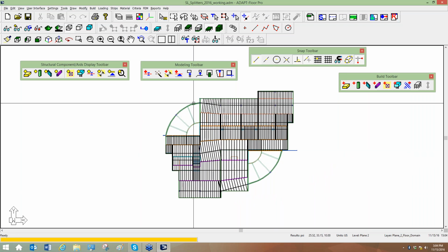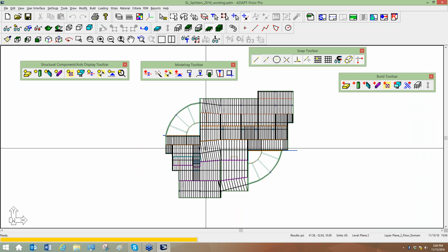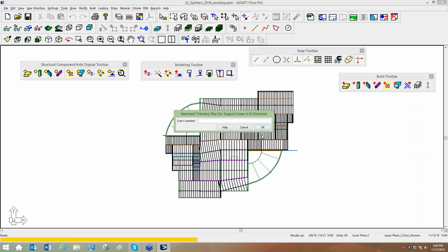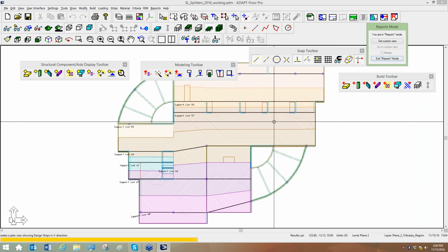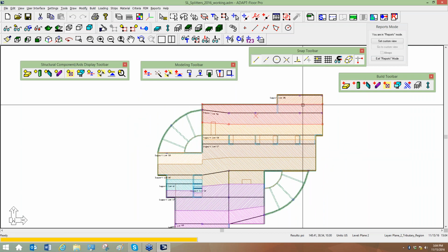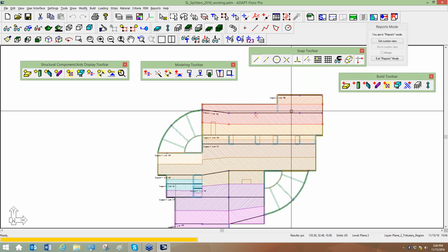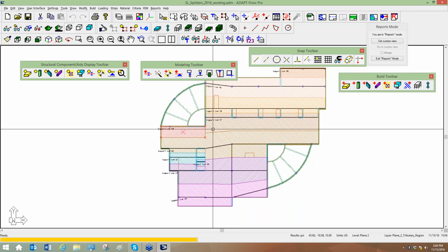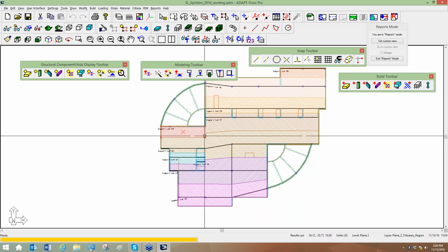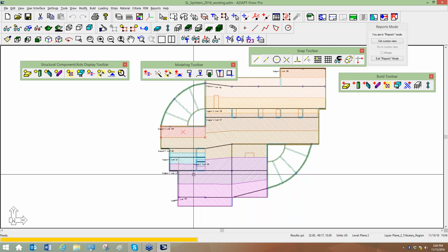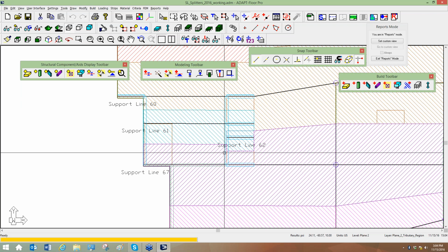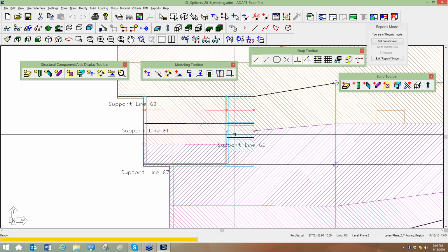Now I have these completely bounded off from the rest of the slab. If I look at my tributaries in this direction, now that we're refining this step by step, I have nice tributaries. Here's that half of that tributary that we cut off with that splitter vertically here, and down in this area, I was highlighting this before, but now we have proper tributaries.